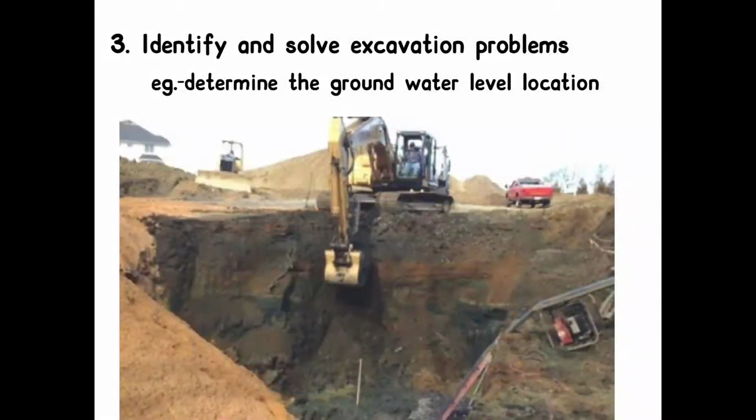Third, to identify and solve excavation problems. Let's say we are constructing a basement for a multi-story building, and for that we are excavating the area. Here we have to locate the groundwater level beforehand so that we can select the appropriate excavation technique, and by that there won't be any cave-in or any other unprecedented situations.